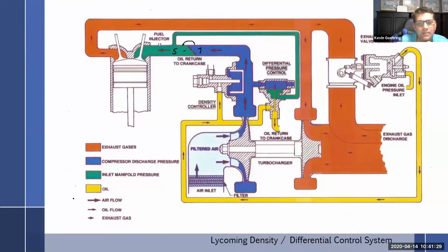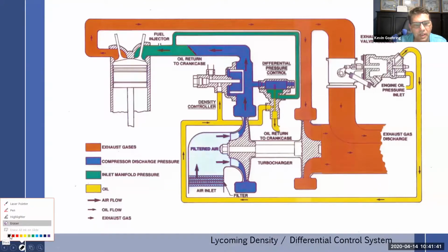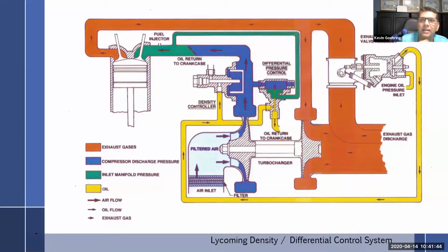But then I decide I'm going to open up the throttle. I've got to erase this. Because we open up the throttle quite a bit, let's say at some point we've got it most of the way open, and we've got 26 inches over here. Well, we'll talk in terms of inches. This over here says, not 2 PSI, 2 inches. This one says, I don't really need to be anything over 28 inches. So it gets to 28, it's going to sense the difference between these two and say, okay, anything over 28, we don't need it. We don't even need 30. Just 28 is fine.